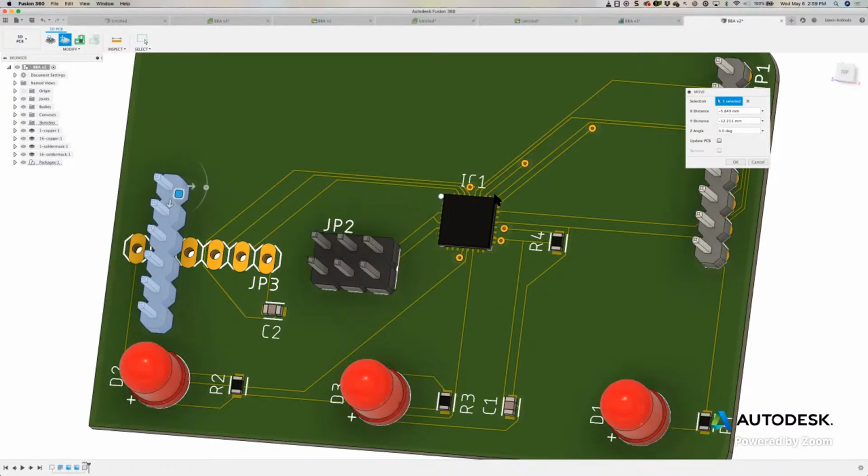Okay, so what I want to do is update the PCB as well as reroute. Click here and there and reroute. Okay, so I'm selecting the option right there. I hope everybody could see that. I'm going to select the PCB and reroute and select both options. The idea is for it to actually update the 2D PCB, come back to the 3D PCB to do the updates. But in the 2D PCB, it's actually going to reroute. That way, all these lines that we have here will now have a new path automatically for us. So let's go ahead and click OK.